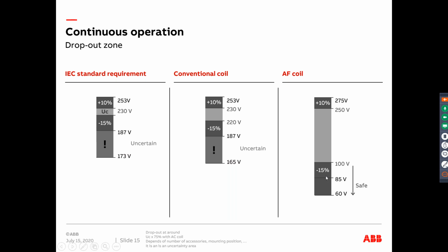Now the safe operating voltage has gone from 60 volts to 275 volts. So how good is it for AF contactors? Even in fluctuations, you can rely on this contactor.